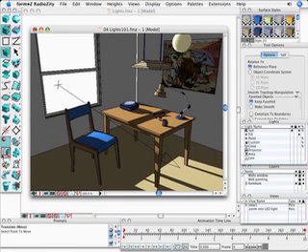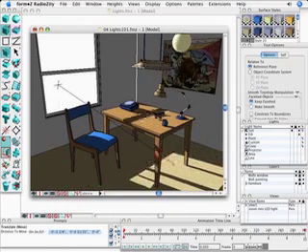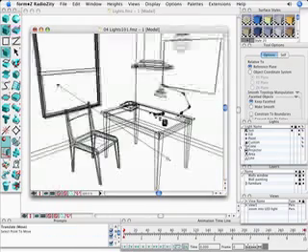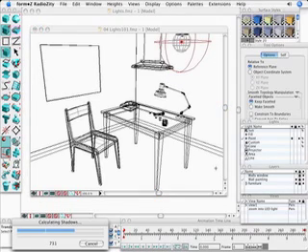Or in interactive shaded here, we can dynamically move these light sources anywhere that we want to change the position manually. Now, some other light sources would be a point light. The point light, for example, the fixture hanging from the ceiling, could be like a light bulb where light will radiate in all different directions from that single XYZ position.